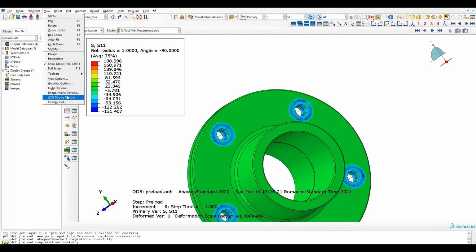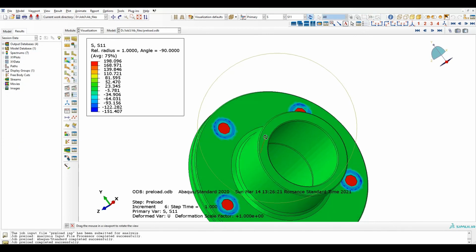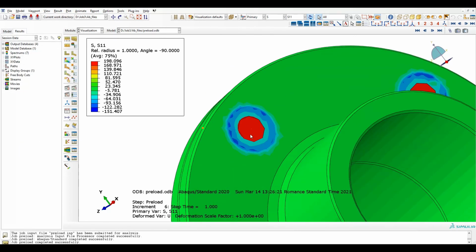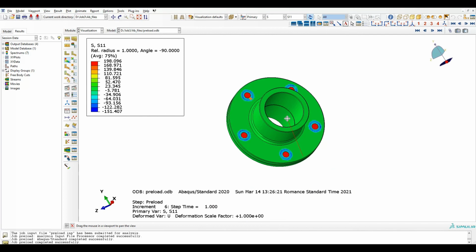We can change the options to see the beam elements. So as the red is on the bolts. So yeah, and that's all. This is a good result. We didn't use CAD elements, so no CAD geometry, just 1D elements. This is a good way to save computational time. Above all if our models are using many nodes.